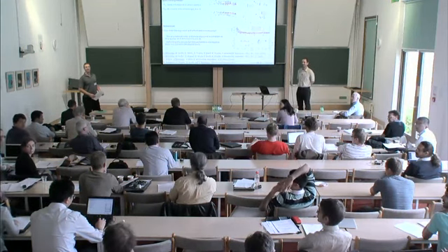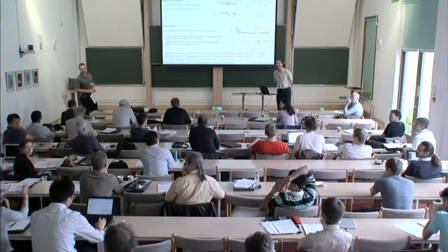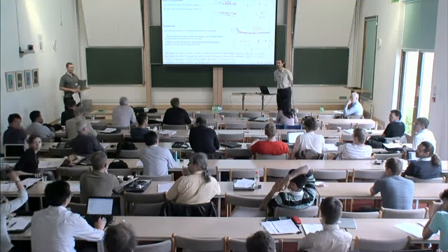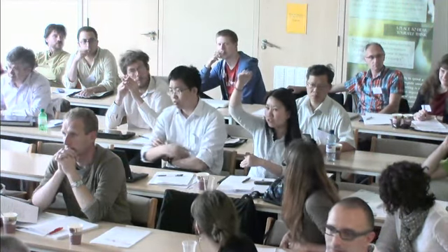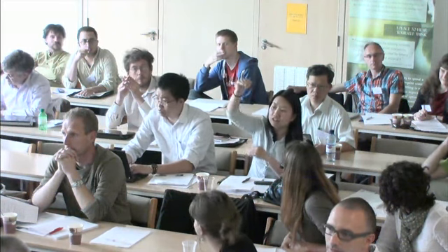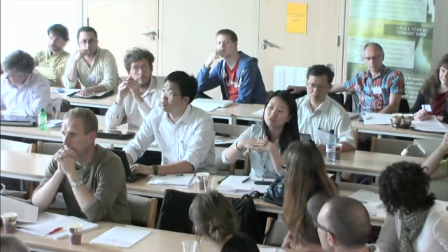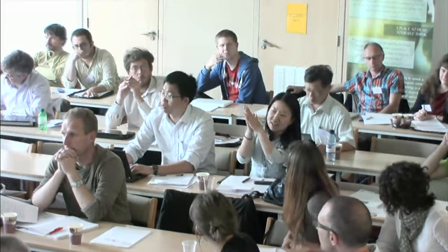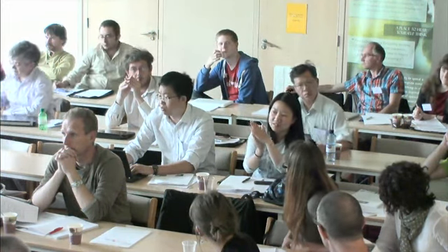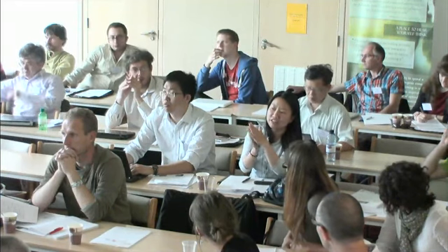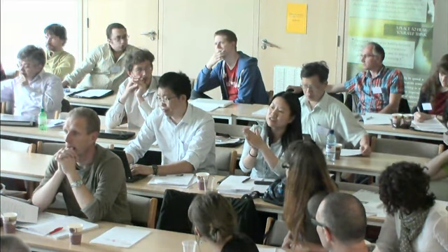That's something we observe in soil mechanics. In soil mechanics, we do lateral and vertical loading, trying to shear the sample while controlling the confining pressure. The general observation is that if we load the sample vertically, we observe the particles tend to be normal to the principal stress direction. But in that very localized shear band regime, the particles tend to be aligned with the very concentrated, higher shear gradient in that localized regime.